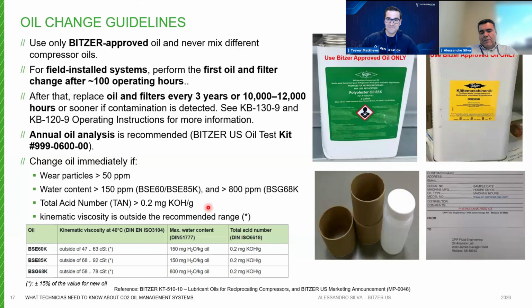We have activated alumina to neutralize the acidity. But of course, multiple oil changes and multiple filter changes are recommended until the system experiences a lower level of acidity. Beautiful.